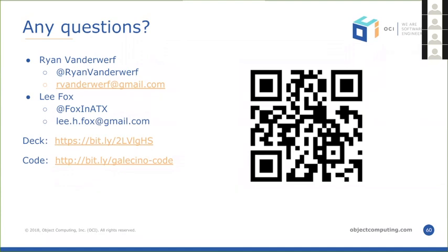For the car, yes. All of the motors, at least, and servos are wired to that PWM controller, including the ground and power being provided, except for the batteries. The Pi is running on a separate battery than the car itself, just because of stability concerns. The Pi does not like large draws taking away its power. So the car has a separate battery pack from the Pi. But as far as signaling, they're all on the same ground, but not as far as batteries.